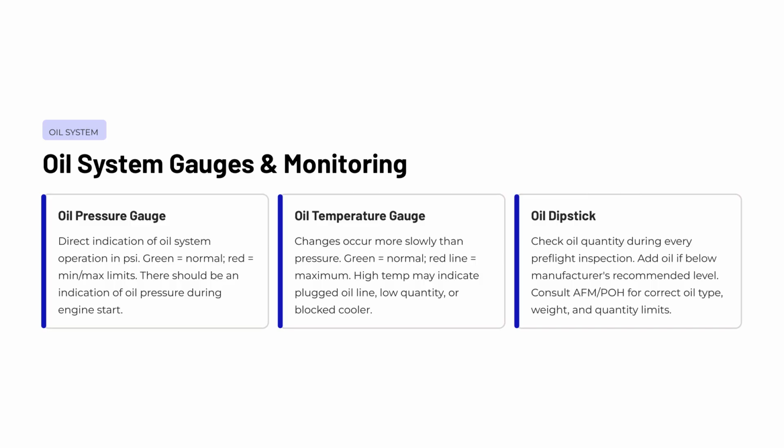During engine start, you should see oil pressure begin to rise promptly. If you do not see an indication of oil pressure within a few seconds of startup, shut the engine down immediately to prevent serious damage. The oil temperature gauge responds more slowly than pressure, so changes can be gradual.